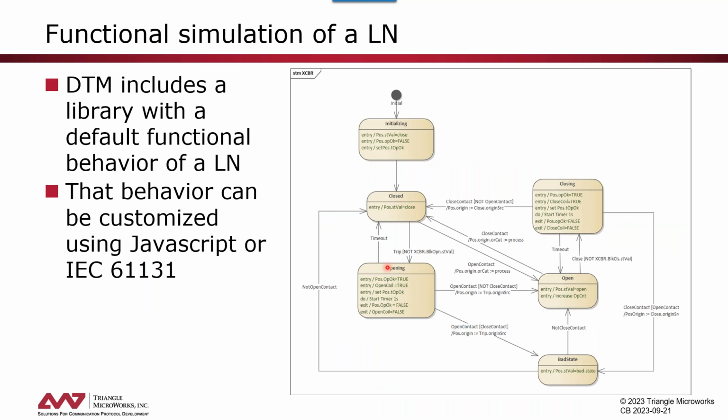To summarize, DTM includes a library with a default functional behavior of more or less every major logical node, as well as major conducting equipment. Here illustrated is the simulation of the XCBR, the behavior that we have in our XCBR logical node simulation. The behavior can be customized, so we have a default behavior available. You can customize that using either JavaScript or 61131.